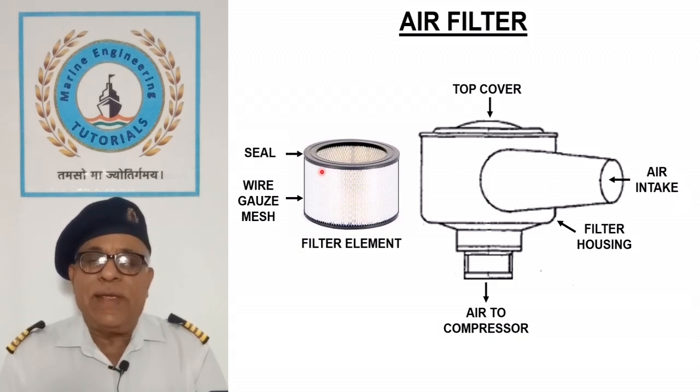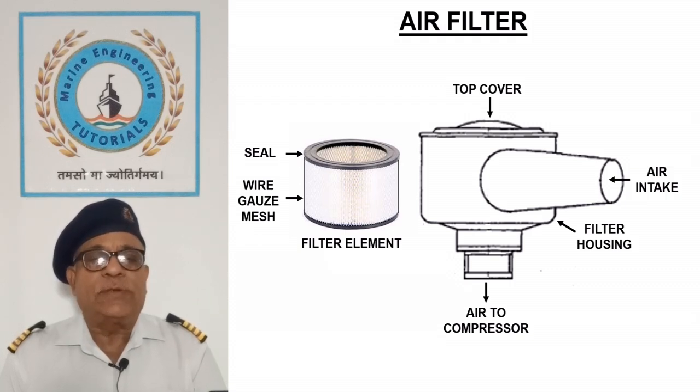Filter is held in place with synthetic gaskets on both faces to prevent bypass of unfiltered air. Air filter in tandem piston arrangement may be equipped with an oil bath for lubrication of LP cylinder with the incoming air soaked with oily vapors.